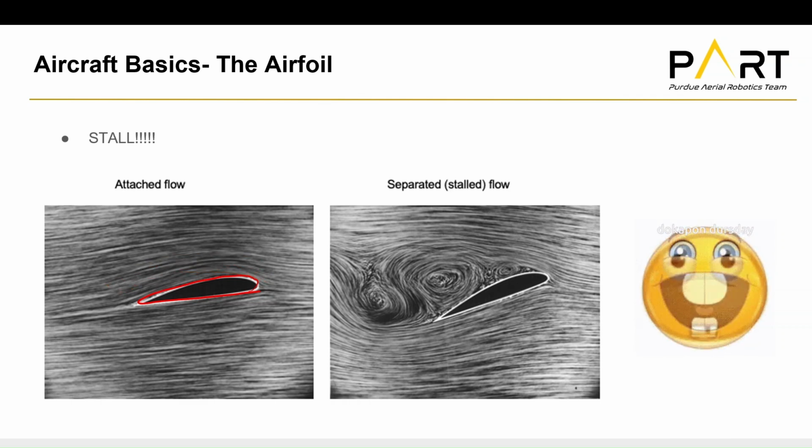Going back to laminar versus turbulent, let's say this is at a 5 degree alpha, angle of attack. Now, when you start hitting about 15 degrees like this, and it's just a guess, but most airfoils stall at about 15 degrees, you get a detachment of your airflow. The physical object in the way of the airflow now has a much larger surface area because it's deflected up.